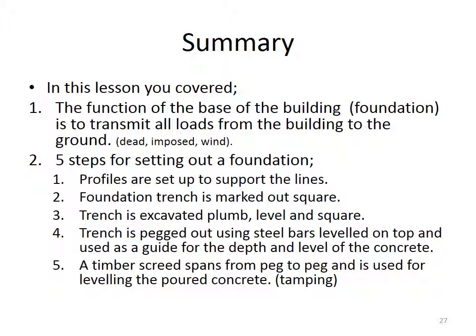Summary. In this lesson you covered 1. The function of the base of a building, or the foundation, which is to transmit all loads from the building to the ground. That includes dead, imposed and wind loads. Number 2, we looked at the 5 steps for setting out a foundation. So profiles are set up to support the lines, timber profiles. Number 2 there, foundation trench is marked out square. Number 3, the trench is excavated either by hand or machine, and the important thing there is that the sides of the trench are plumb, perfectly vertical, the bottom of it is perfectly level, and the corners are square.